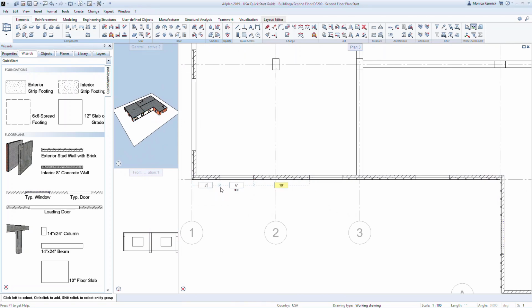For example, in the left box, change the location of the window from 9 feet from the reference corner to 5 feet. Use the center dialog box to change the width of the window. The arrows below control the reference edge so the program knows which side to modify if you're changing the width of the window. You can also use the snap points to drag the width of the window or the location of the opening.